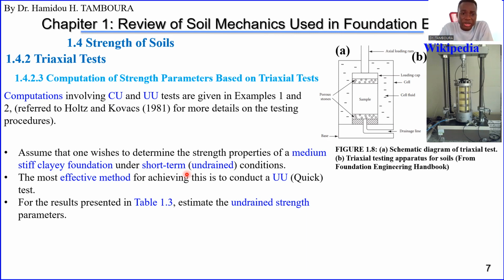So the most effective method to achieve this is to conduct the UU test, which is a quick test actually. So UU, unconsolidated and undrained triaxial test.